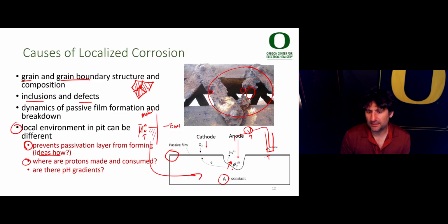Now, if the potential is higher in the pit, that's going to effectively make it so that electrons are going to want to flow more readily into solution. So a higher positive potential in the pit, which is driving the cations out, is going to lower the solution potential relative to the metal. So that's going to actually make reduction reactions more favorable.